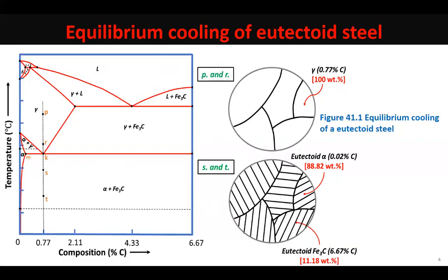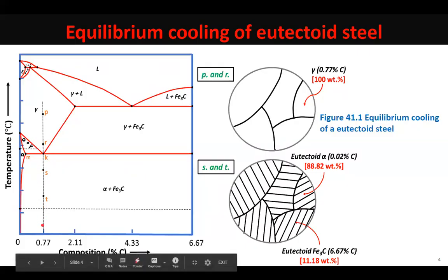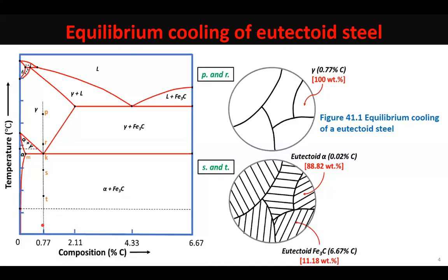the mass ratio of ferrite to cementite is 8:1. Their densities being about the same, their volume ratio is also 8:1. So we generally show the ferrite lamella about 8 times the width of the cementite lamella. Students, even when the steel is now cooled to lower temperatures down till the room temperature, there would not be any change in the microstructure of the steel.